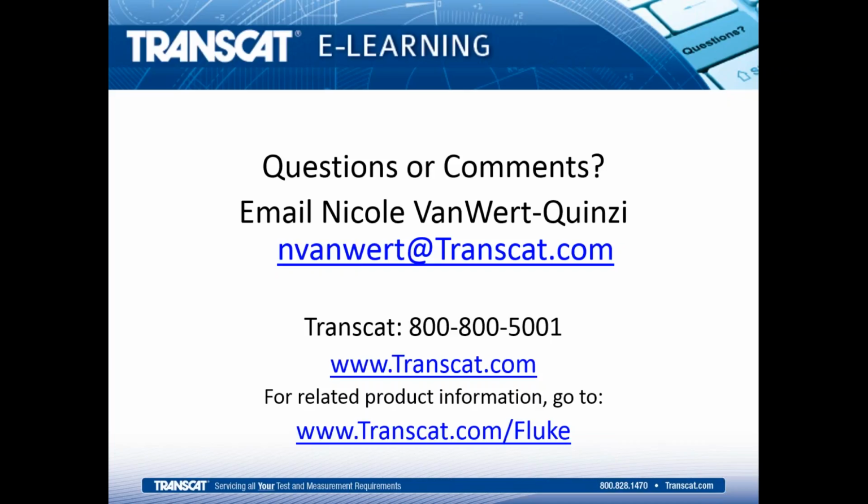Okay, and the last two here, they're both application related. Is there a technique for accurately testing temperature switches, and then can you use dry wells for calibrating surface mount RTDs? Oh, okay. So for temperature switches, actually most of the Fluke dry blocks have got a connection for being able to do a temperature switch calibration, where you wouldn't have to have a separate DMM.